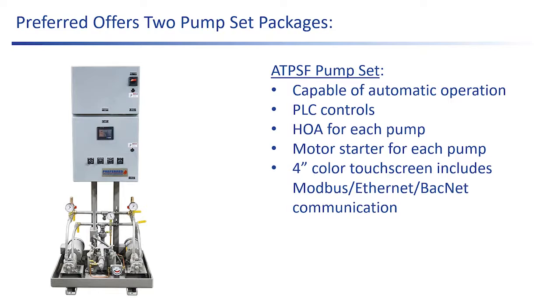And the number one reason why the flow switch won't prove is that somebody has closed a hand valve and wasn't aware. So, hopefully the boiler technicians will line up all their valves before they try and fire on oil, but sometimes they forget a valve and miss a hand valve. It happens to the best of us.